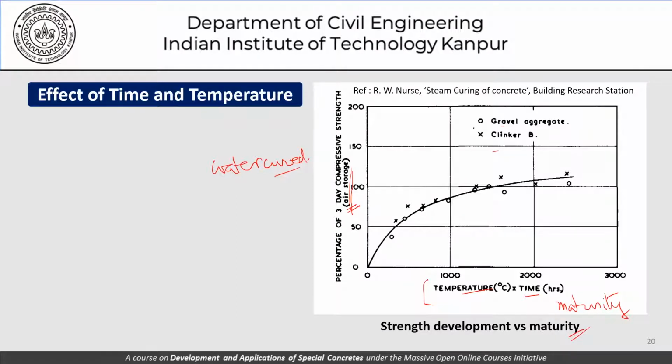The bottom line being that in these kind of discussions, it's very important to properly understand the concept of maturity and make sure that we have a right kind of estimates being made as far as the concrete strength is concerned, because that will essentially determine our handling protocol, that okay, what is the kind of strength that we expect in the member at a particular date or in a particular time, so that we can subject it to